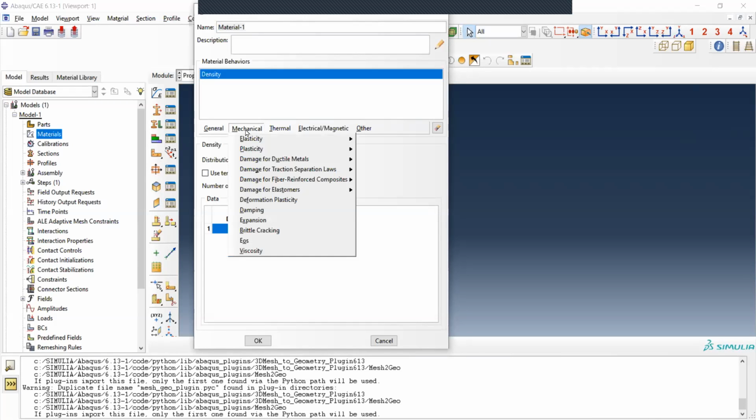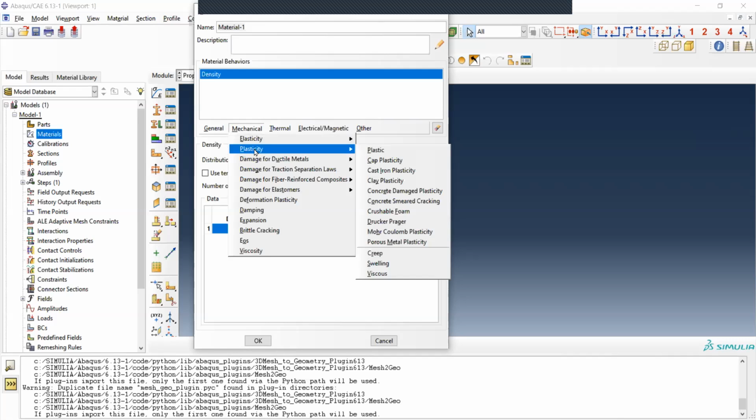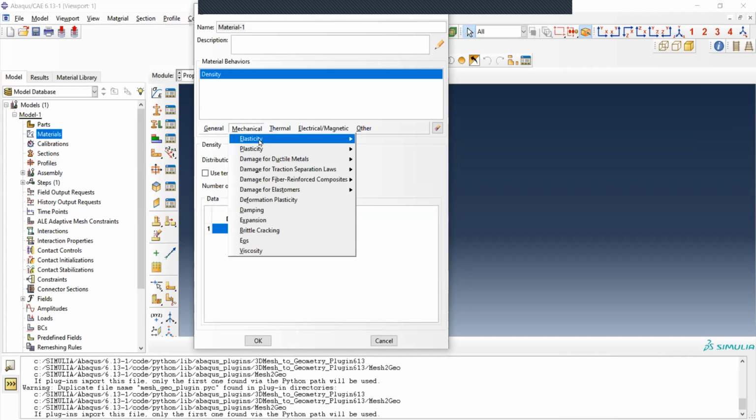But what we care about in this simulation is the mechanical performance. That's why we only need to simulate it with mechanical properties, and just to simplify, as an elastic material without adding the plasticity deformation. So we assume that everything must remain elastic, and the stresses should not reach the stresses that induce plasticity. I assume as mechanical engineers, you understand what I'm saying. So mechanical, elasticity, and just a standard elastic material.